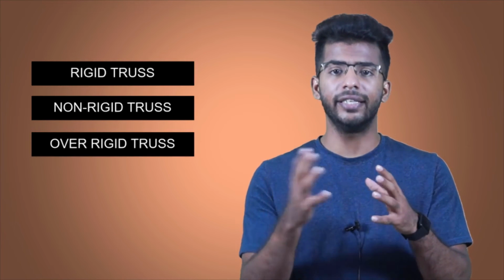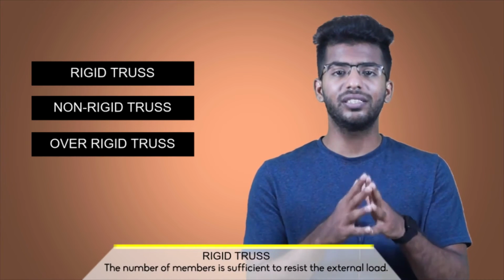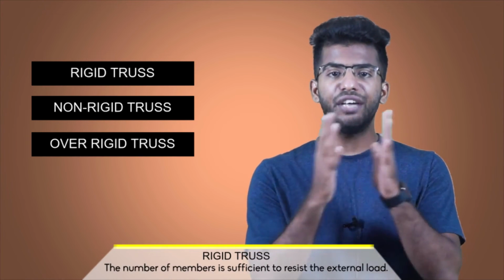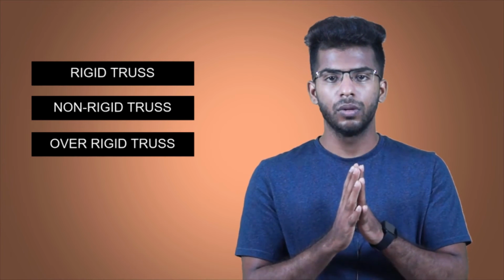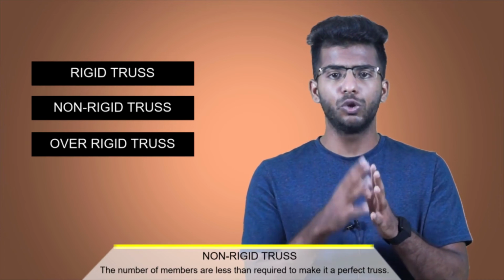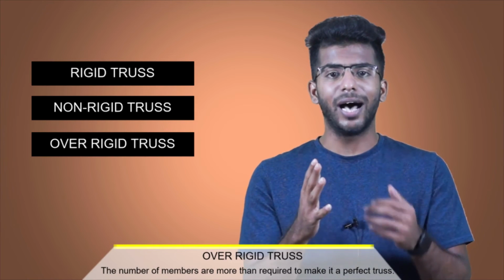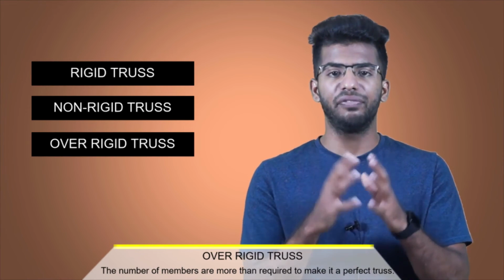The trusses are also classified based on the number of members. So, we have rigid truss or perfect truss, non-rigid truss or deficient truss, and over-rigid truss or redundant truss. In a rigid truss, the number of members is sufficient to resist the external load. The deformation is minimum. In a non-rigid truss, the number of members is less than required to make it a perfect truss. In an over-rigid truss, the number of members is more than required to make it a perfect truss.